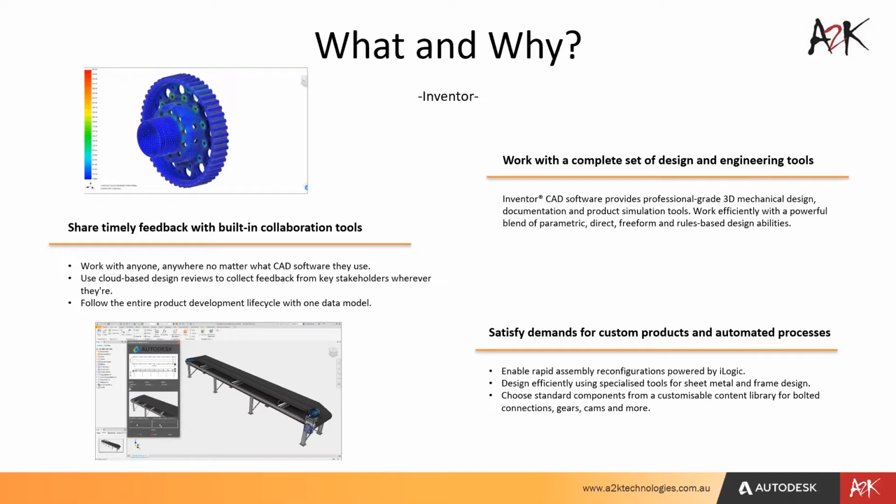It has a number of different flexible modeling options to allow you to use the right modeling tool for every job, be that parametric modeling or direct modeling, which allows you to push and pull controls to move, rotate, resize, or scale features from imported geometries, or even freeform modeling, where you can freely sculpt and shape your design by moving points and edges and faces around. Okay, it's got plastic part design and plastic part molding.